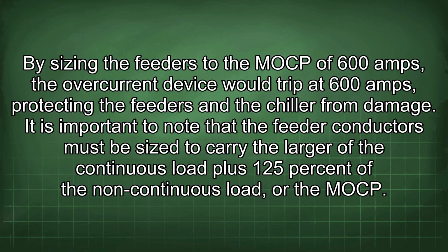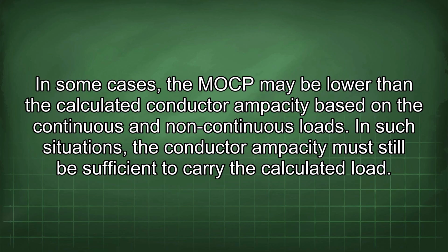It is important to note that the feeder conductors must be sized to carry the larger of the continuous load plus 125% of the non-continuous load, or the MOCP. In some cases, the MOCP may be lower than the calculated conductor ampacity based on the continuous and non-continuous loads. In such situations, the conductor ampacity must still be sufficient to carry the calculated load.